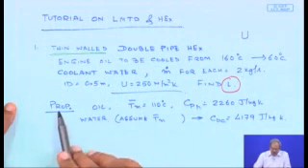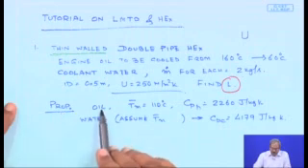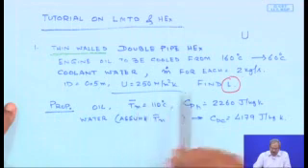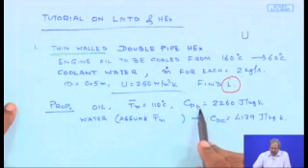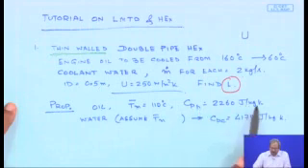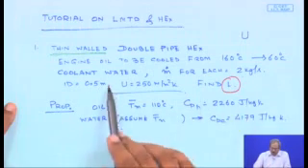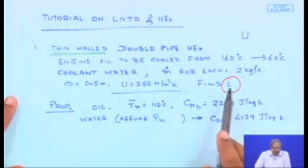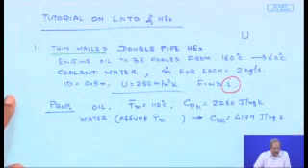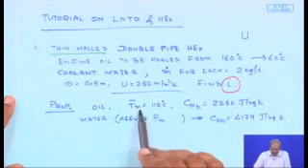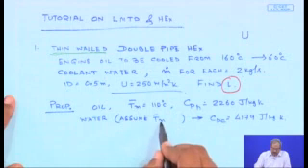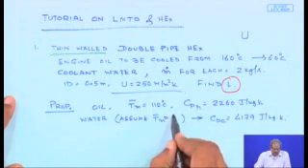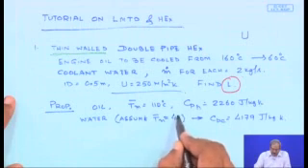In order to do that, first we need to find out what are the properties, and the properties can be found from your textbook. So if I consider oil, the average temperature is the average of these two, and at that temperature the value of the specific heat can be read from the table in your text or will be provided. For the coolant water, we do not know what is the coolant mean temperature going to be. So we are going to assume an average Tm, average water temperature. Let's assume this to be 40 degrees centigrade. It's not going to matter much.